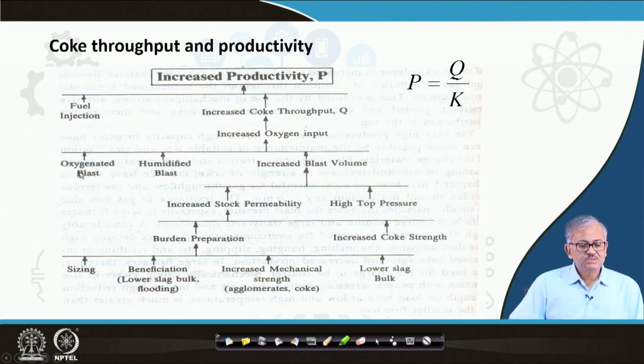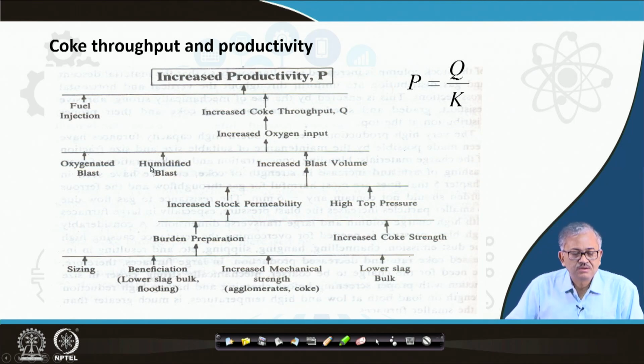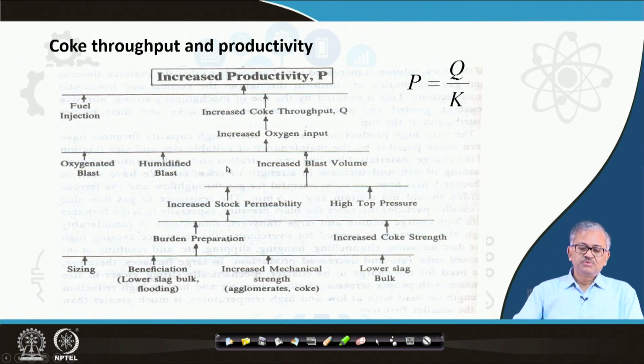Now oxygenated blast, no problem. Humidified blast, you just inject the moisture, that is possible. But if you increase the blast volume, that is not that easy, as we talked about at the beginning. If you want to increase the blast volume, then a pressure problem comes: the pressure drop will increase.